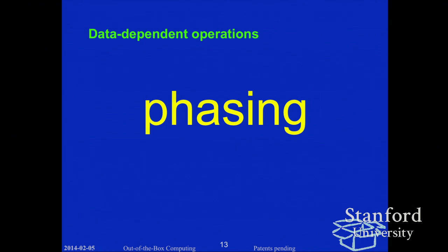Going to talk about phasing. Operations connect through data flow paths such that the result of one operation is the input to a next. And the chain of such items is a data flow, frequently a data tree, but for most of what I can show on a slide, you can only fit so much on a slide. We're going to be looking at linear data flows rather than trees. A consequence of the way the mill is organized is that we are in fact able to execute faster than the clock rate would appear to make possible.